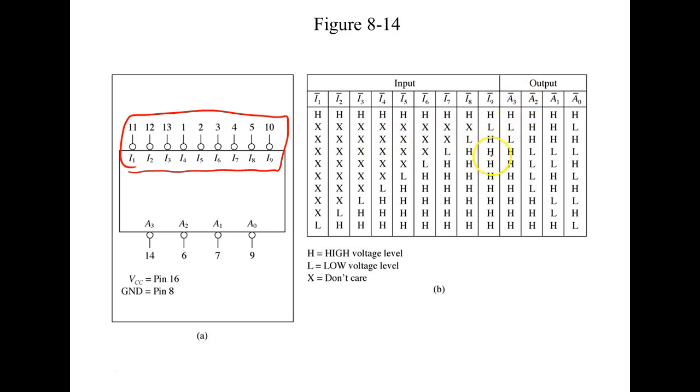So here we have, and this is a low active input, guys. So we would think a 9 would look like that. But if it's low active, then a 9 is going to look like that. So a 0 is true, right? So this would be a 9. And which output went low? I'm sorry, this is the inputs, Rich.